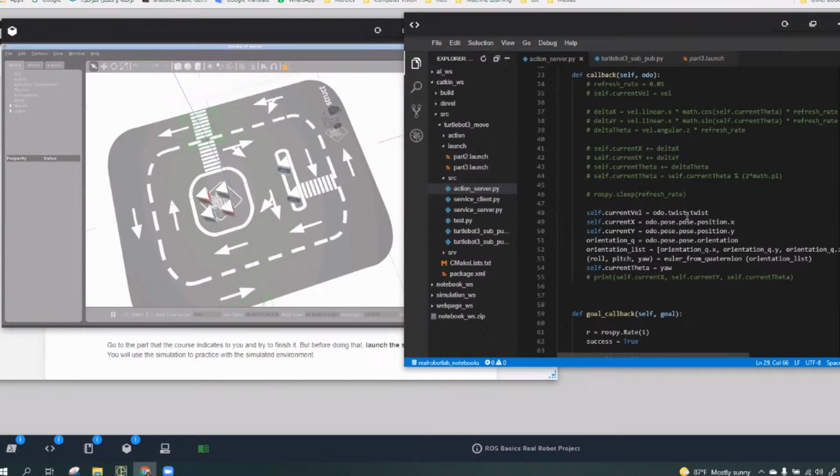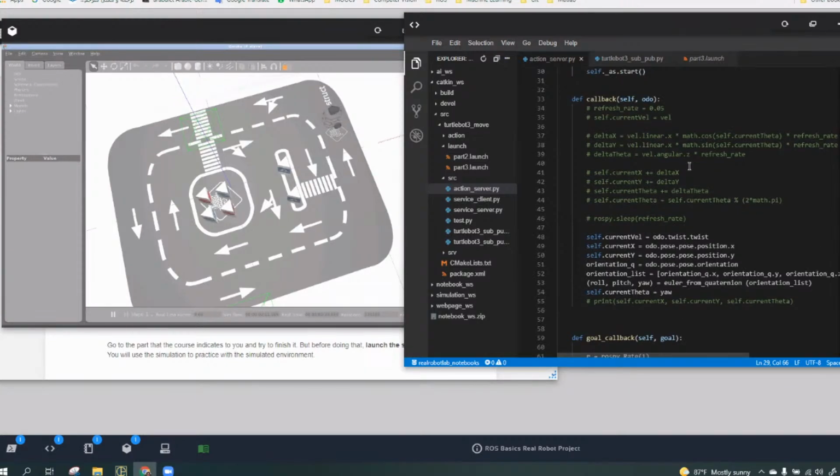Yeah, sure. I thought about it like an imperfect Riemann sum. So I tried to integrate the cmd_vel in order to get the odometry values. The reason I prepared this solution is that, as you said before, the odometry was not working as expected. So I tried to make my own solution.